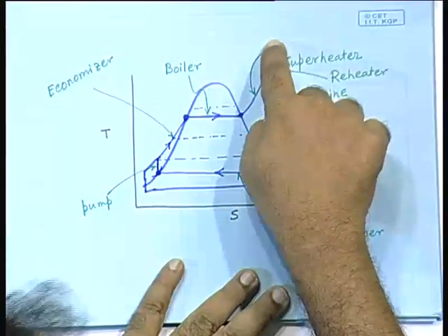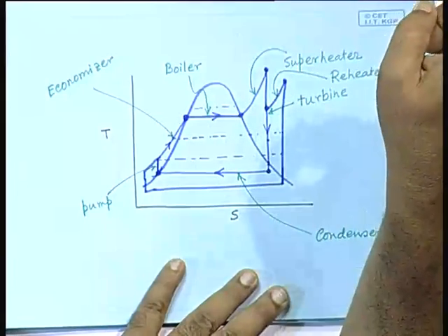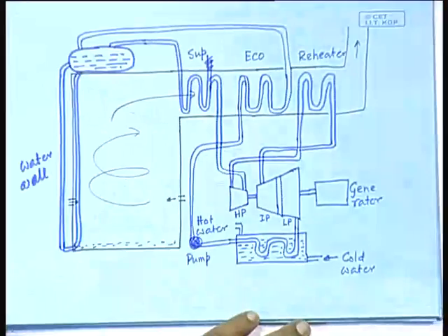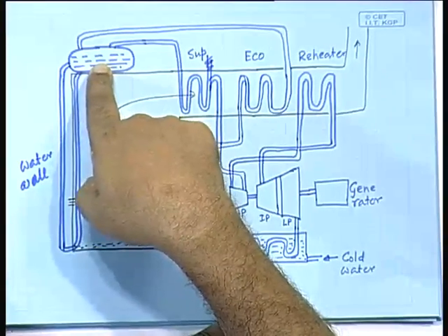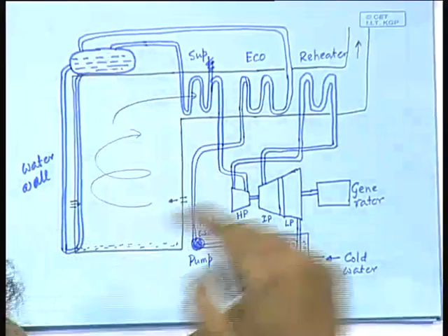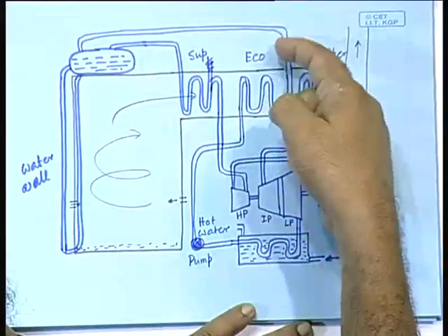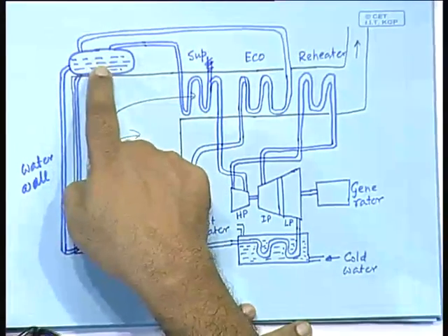There are, but I will come to those things a little later. One thing is to bring the temperature or pressure here further up, and those, as I told you, cannot be done if you use a boiler drum. So, some of the super thermal power plants today use no boiler drum, and in its place there is, after the economizer, a pump that circulates it through the water walls instead of the natural circulation from the boiler drum.